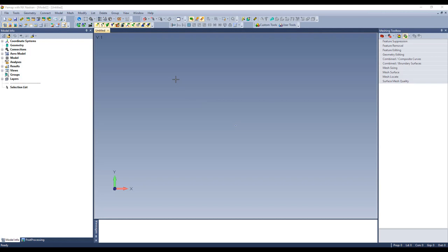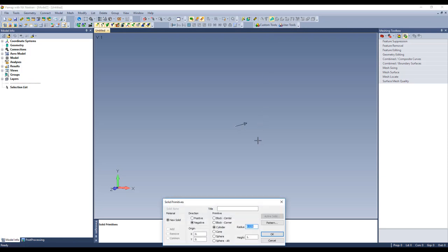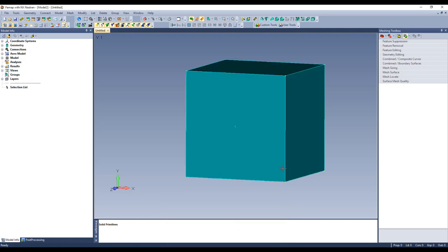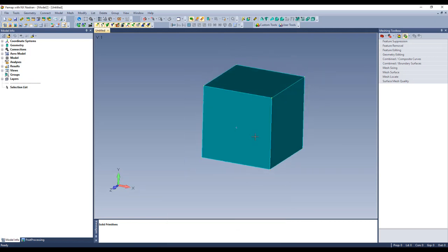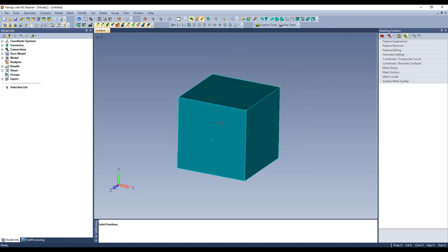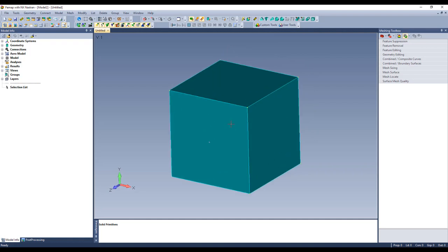Welcome to Femap version 12. I'm going to go over some new features, some old features, some new solver features, and we'll build a little test model about the heel and toe loads you can get on bolts, where a little prying action will increase your bolt load. Let's go ahead and start off. Let's make a little angle clip, and we'll model it to investigate this effect.